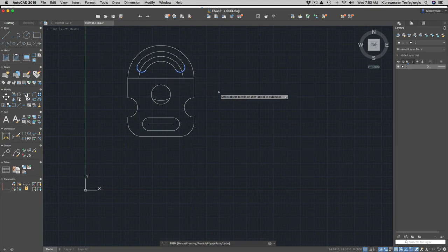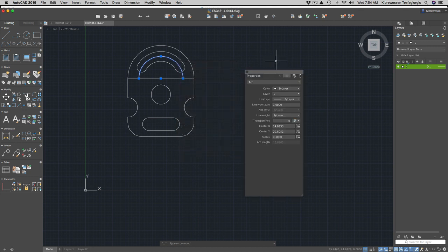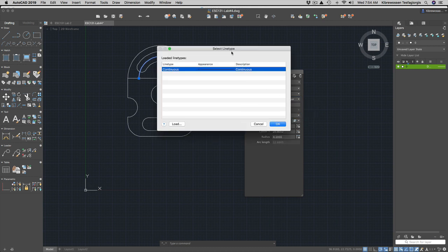Then the line types and whatnot, you can have them later. For instance, you can change the line property of this. Okay, this line isn't there. I'll just show you, for instance, you can right click and go to properties, and you can see a line type is of course by layer, but we can change the line property.